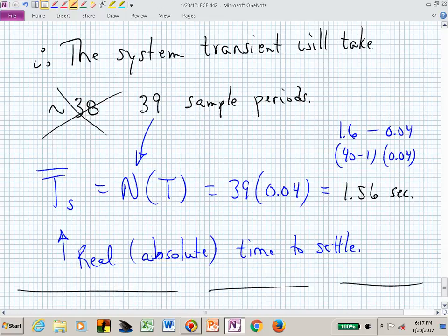Yes, so now if you have an actual system, if this is a continuous time system, the A matrix, the B matrix is going to hinge on the sample period that you select. And what did we say leading into this lecture with one of our goals? What did we say the sampling period might be for a generic system? 30 times the closed loop bandwidth.